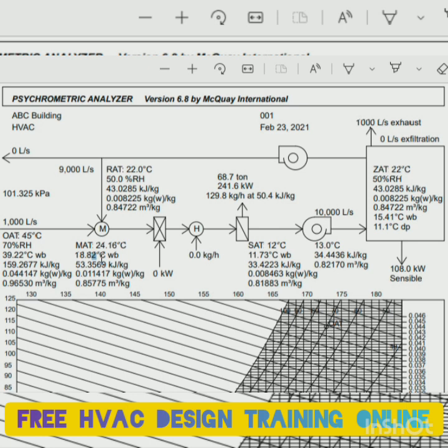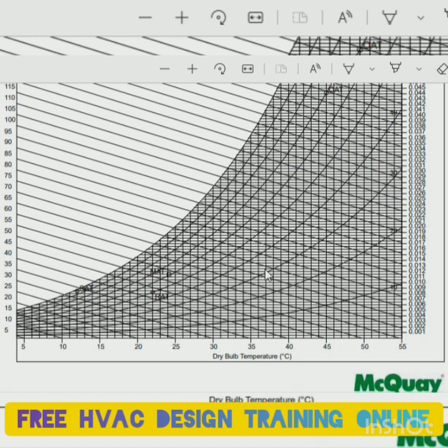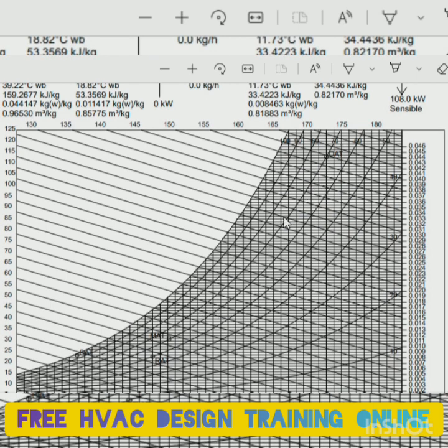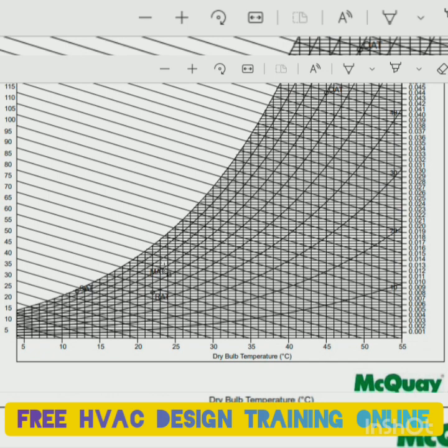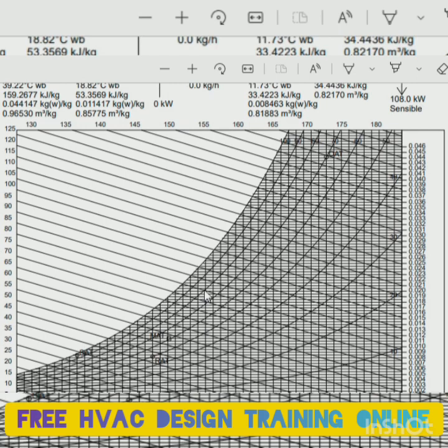And this is your off coil temperature. The difference between the room temperature and this temperature should not exceed 10 degrees Celsius. Try to take 9 degrees, 8 degrees, or 10 degrees maximum. And you can very easily explain this to your client: what the outside air temperature is, what the return air temperature is, what we are going to maintain as the mixing air temperature, and what the supply air temperature is.